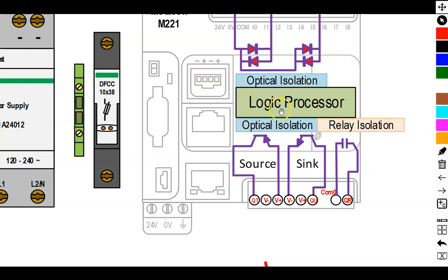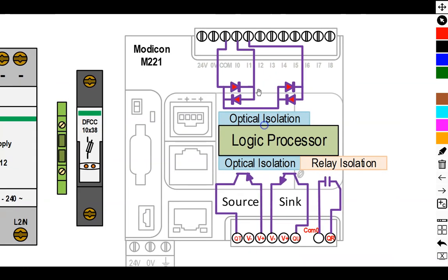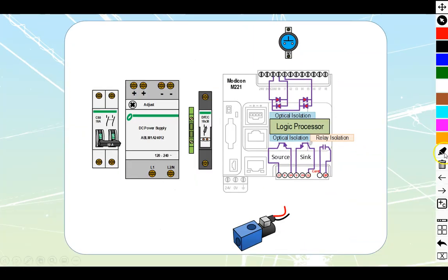This is simply explanatory. On the PLC itself, you'll note that I've grayed out my PLC in the background over here and that I've applied this purple wiring over top. And this purple wiring just shows the internal pathways for power to circulate through here. This is my common terminal on my input side over here. And you'll see that that common terminal is going to go, if I zoom back out here a little bit, over to both of these groups of internal LEDs.